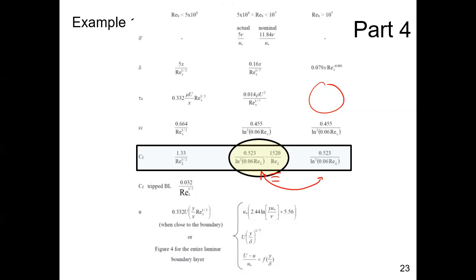You cannot solve these problems unless you know the boundary layer characteristics. And every part that we've done in this problem, the first thing we do is calculate the boundary Reynolds number. That unlocks the equation you need to use on this Rosetta Stone. If this is one of your sides of your crib sheet on the final exam, that's fine with me. All of these equations are in your book.